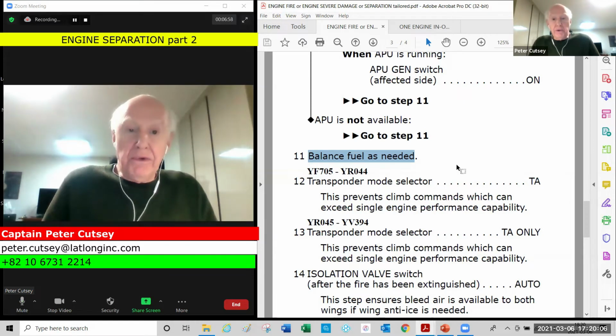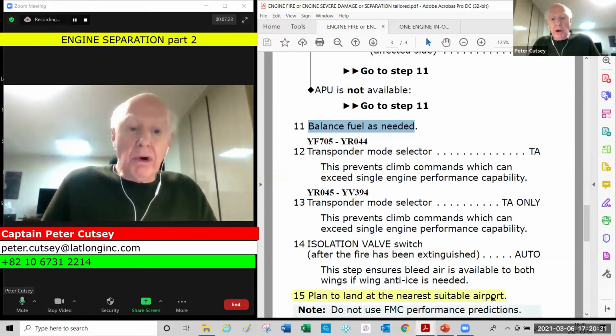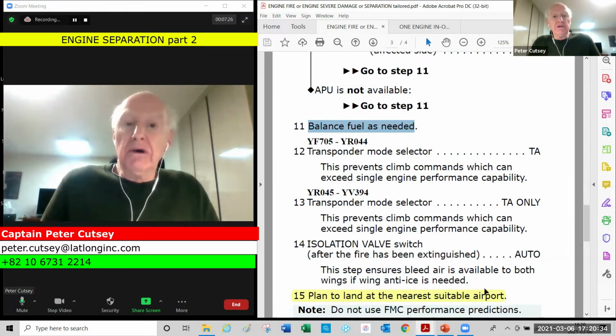If you suspect a fuel leak, then you had better not do it by memory. In any case, your company SOPs will dictate what you should be doing if the imbal light is not on. The imbal light is on, you have no choice. And you may want to do that checklist prior to doing any more on this checklist, depending on how severe it is and how long you've been flying on one engine. So this is where airmanship comes in.